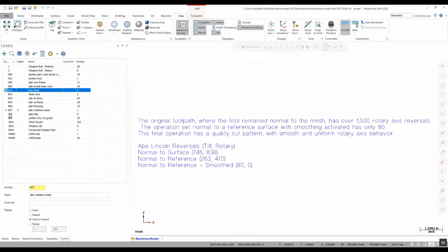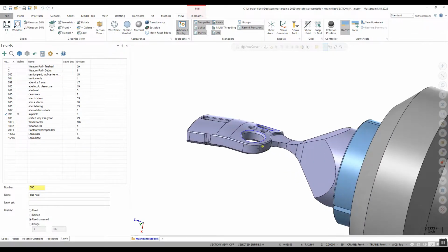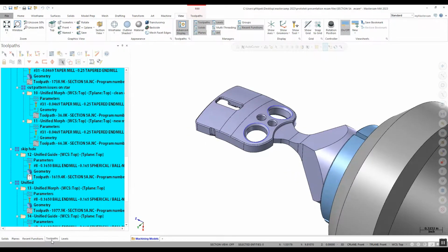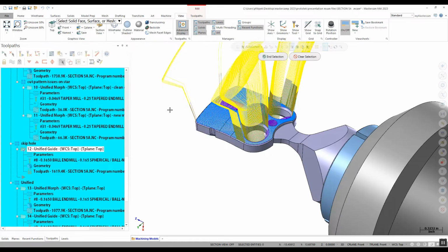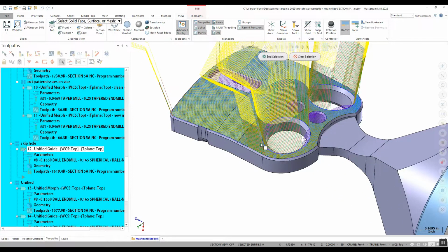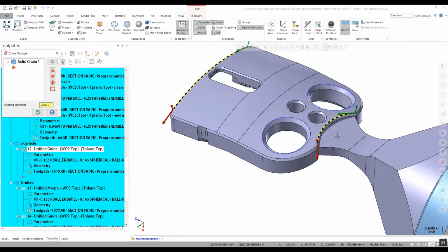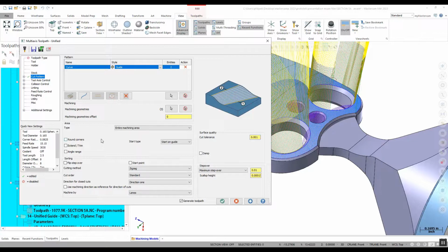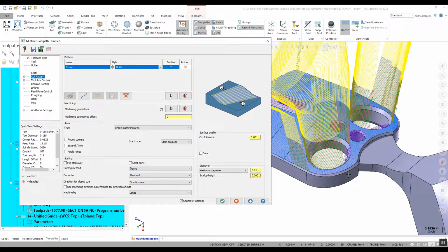And then Skip Hole. Skip Hole's a pretty quick one to take a peek at. Skip Hole can be nice, especially bone plates is where this really comes into play for me, I would say. And here's a situation where I'm just going to do a multi-axis toolpath. I'm going to do these 3 surfaces here. And I'm going to guide it against 2 guides, a guide there and a guide there. Now, as we can see, it gets to a hole, and essentially I have a mess, right?